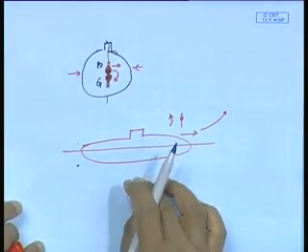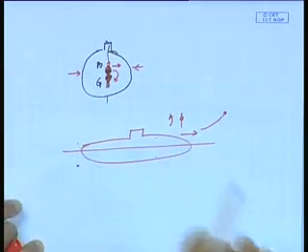So, why is this important? Therefore, you cannot study the horizontal turning or vertical motion without the coupling for submerged bodies. You cannot say in isolation, I will make it turn, because as it turns, it spirals down, since horizontal motion necessarily produces vertical force. Vertical may not produce horizontal because of port-starboard symmetry, but horizontal does produce vertical always.